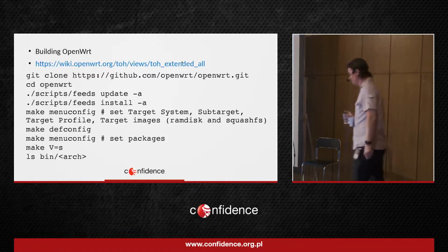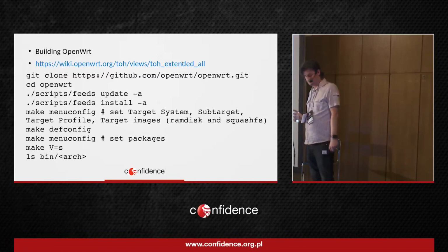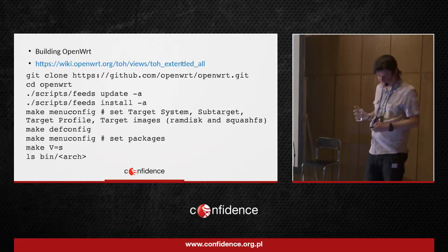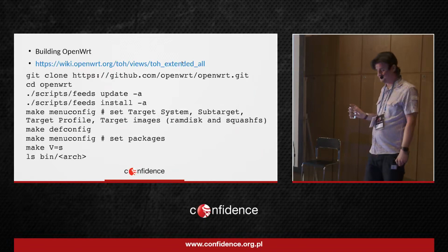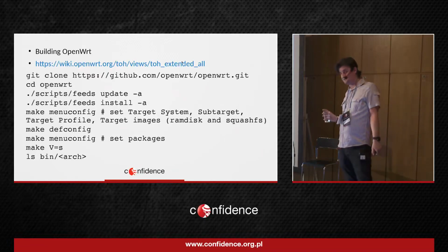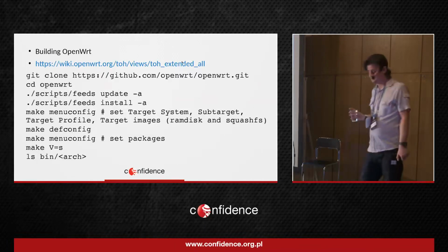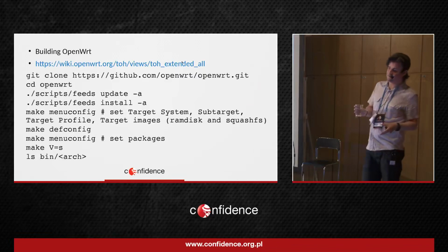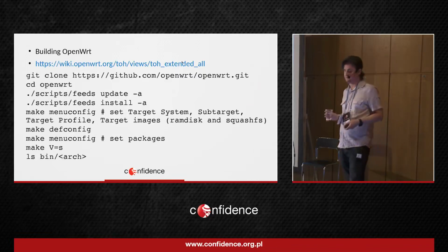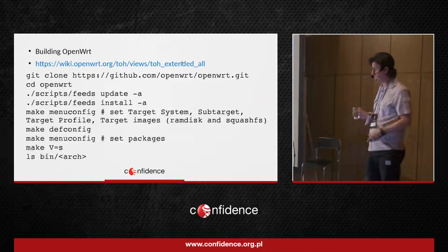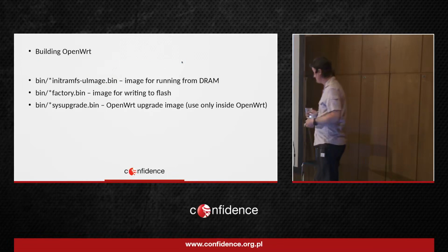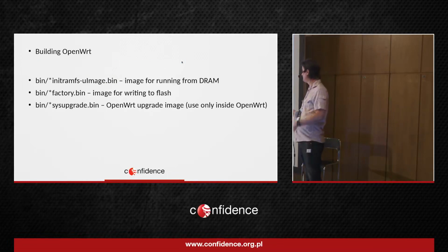It's very handy because the build will fail. It's very easy to fail a build. For example, the most common case is when the built image is bigger than the Flash on the device, or is bigger than the RAM that we have. So please don't put a Python interpreter or GCC in the image, because it will simply not build and not run.